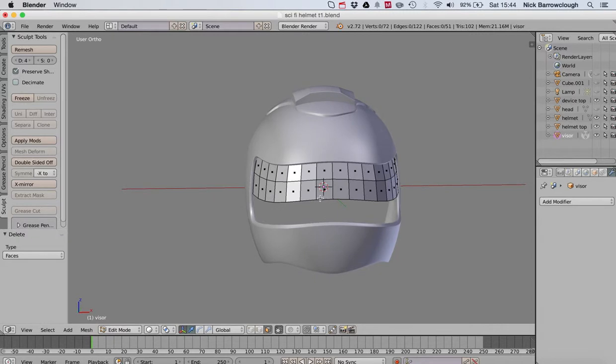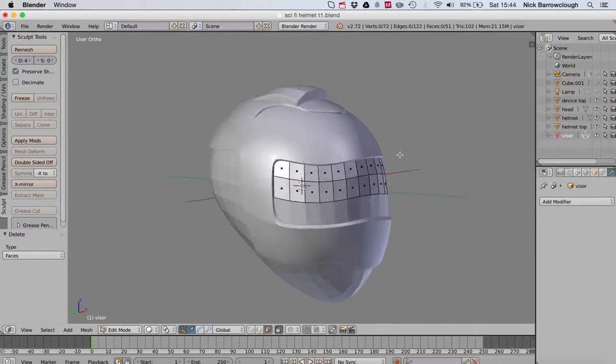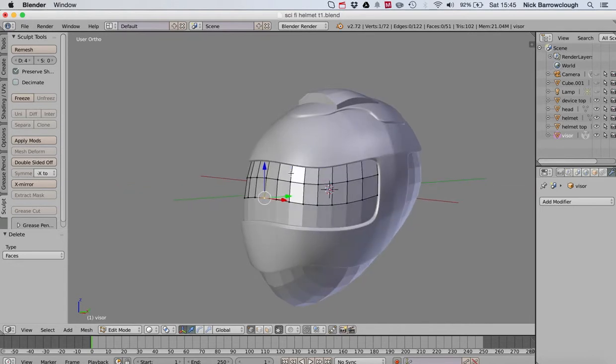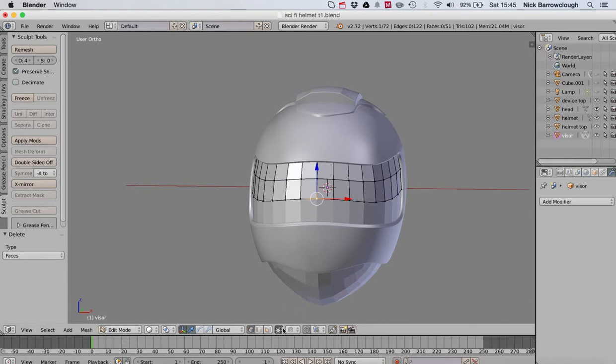Now I want to actually create an area here where the nose would be, so let's put our head back in. So the nose would probably be somewhere around the middle here, so we'll grab our vertexes and let's move this vertex, but we're going to snap it to the surface of the object behind so that it's not going to snap to the face.